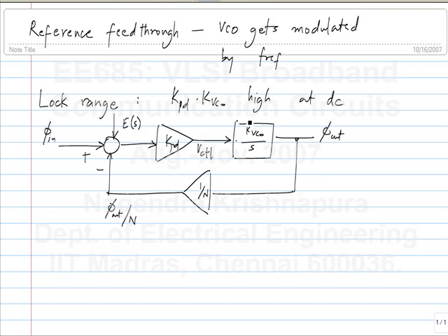Okay. So, is there some way to break this deadlock? So, you have KPD to be high, yeah. Put some kind of filter in. KPD to be high and put some kind of filter in between. So, essentially this KPD should not be constant. Let's say instead of a constant we express it by a transfer function. So, you are saying the transfer function should be like what?